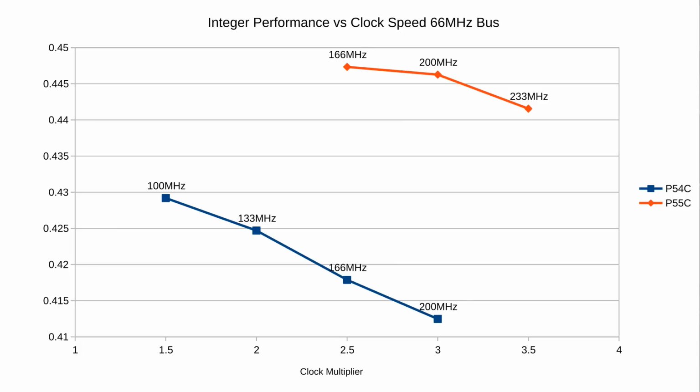Second, the whetstones per clock still decreases as clock speed increases, but it decreases at a much lower rate. While this is significant, it kind of just reinforces what we already believe to be true, and that's increased L1 cache size decreases the dependence on the rest of the memory hierarchy.